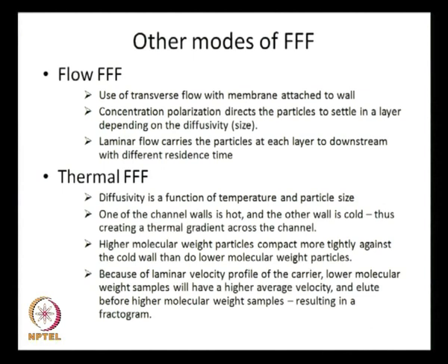There the bottom wall and the top wall are at different temperatures. Diffusivity is a function of temperature and particle size. So, if one of the channel walls is hot and the other wall is cold, thus creating a thermal gradient across the channel, then you can accomplish this thermal FFF. Here, higher molecular weight particles compact more tightly against the cold wall than lower molecular weight particles, and again because of the laminar velocity profile of the carrier, lower molecular weight samples will have higher average velocity and elute before higher molecular weight samples, resulting in a fractogram.